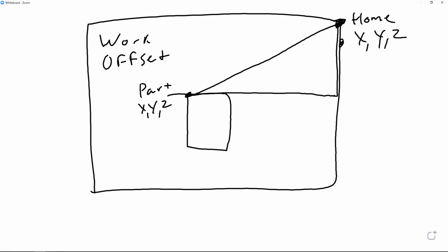And in our case, for a lot of cases, it's going to be G54 through G59. If you need more than that, there are other options on the controller. And this is just an area in the controller. On the offset page, it'll be listed work offset. And that is a data, that's where you edge find. That is 00 for the program. It takes care of these offsets for you.